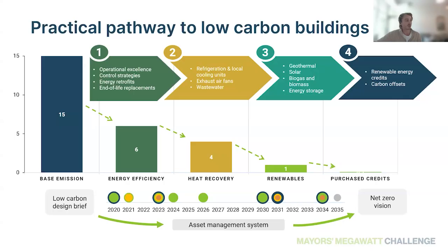So we want to ensure the building is operating with that low-hanging fruit addressed, before you get into the major capital investments. You want to make sure the building's operating as efficiently as possible. The reason for that is you don't want to spend extra money on a 10-ton unit when an 8-ton unit would do. Once you put those efficiency measures in place, your 10-ton unit would be operating at a poor location on its part load performance curve. So you want to make sure the building is operating as efficiently as it can be, whether that's through outdoor air scheduling or various measures that we'll discuss in the coming slides.